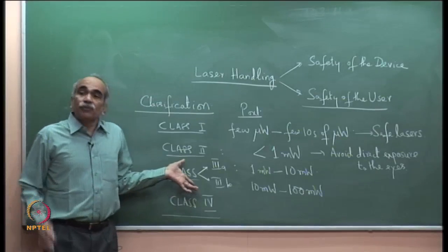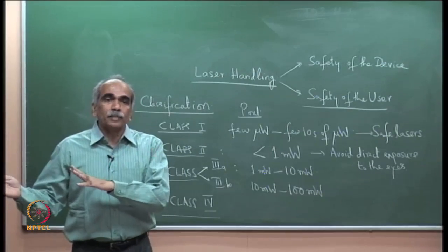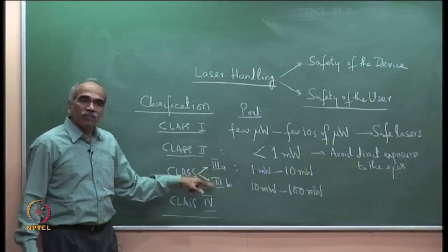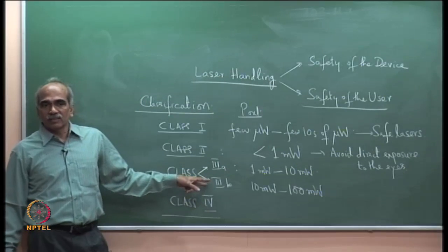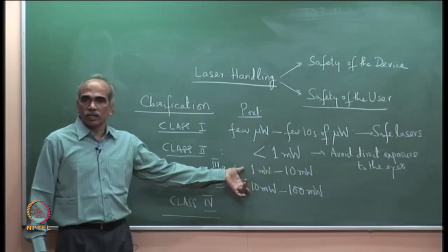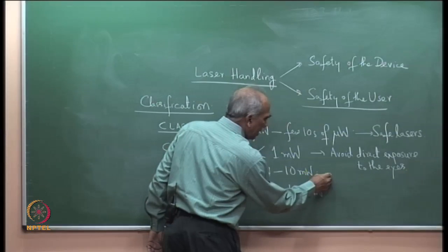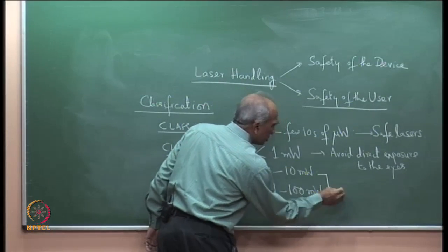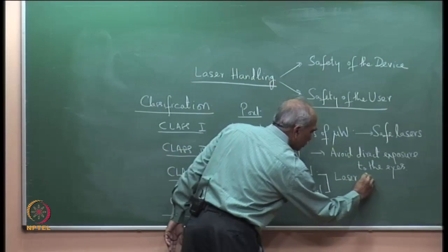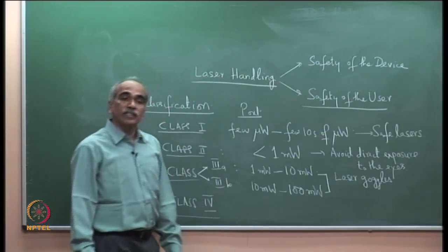But these are the approximate power ranges. Most of the lasers which we handle in applications other than maybe in nonlinear optics experiments or in industrial applications, we handle class 3A and class 3B lasers. In most of our laboratories, communication applications, the powers involved are class 3A and class 3B. So, class 3A and 3B here, eyewear is a must, laser goggles. Wear laser goggles or laser safety wear.